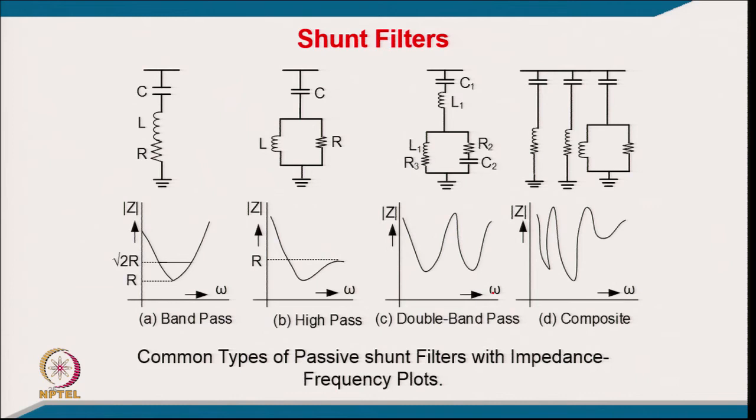Or it can be the composite which we have shown earlier. So, you have a composite meaning a two tune filter, maybe fifth and seventh, and then you have a high pass. So, you can clearly see fifth here, seventh here, and all higher harmonics correspond to this filter. So, 2 of this category and 1 of this category, and this is the actual composite we use in practice.